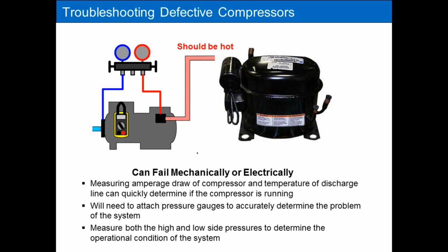Now it's time to dive into the system in a little more detail. You may need to put those stubby gauges on to see what the problem is. Is it loss of refrigerant? Is it a compressor that is not pumping? Or is it a plugged cap tube? But at least I know I got a problem. I got a serious problem here because my discharge line is not warm at all, or not hot, and my compressor is consuming current. It's running. So that's my usual first test.